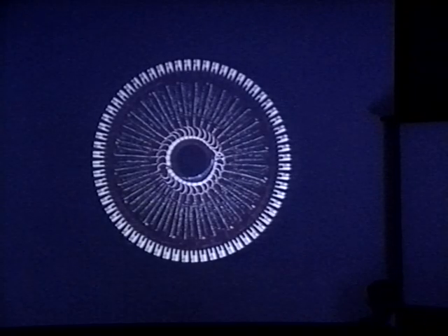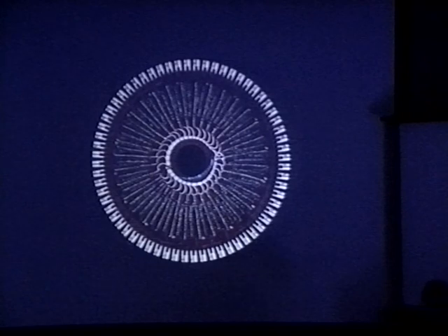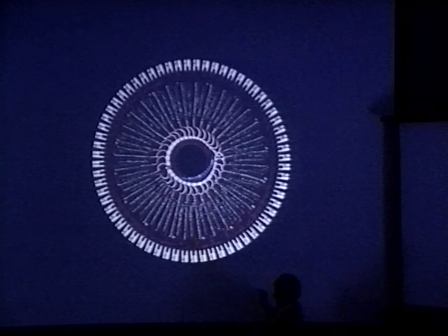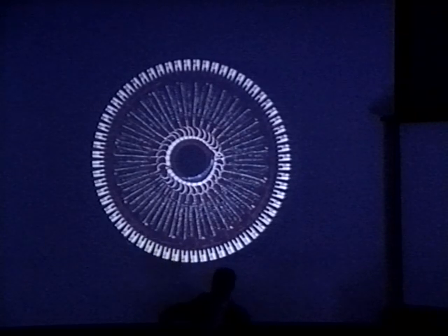Now that was the device we came up with, the scale. You can see it right here. So this was our first effort at a transformer read-only memory. The transformers are on the circumference, 64 of them. There are 30-turn windings here to carry the sense signal out from this circumference. The drive wires, which I suppose you can't see at the back, are all these things here. They start at a point such as that, go through a transformer, come outside, and we provide a rim around this wheel for wires that are not going through transformers. They sit in that rim.